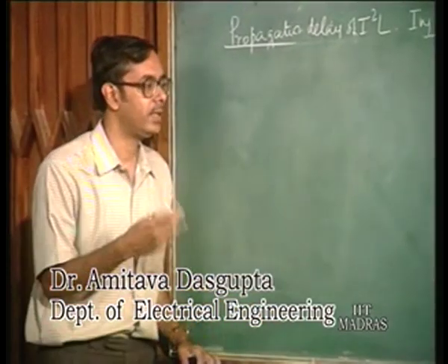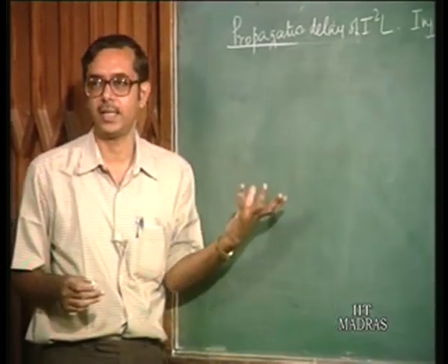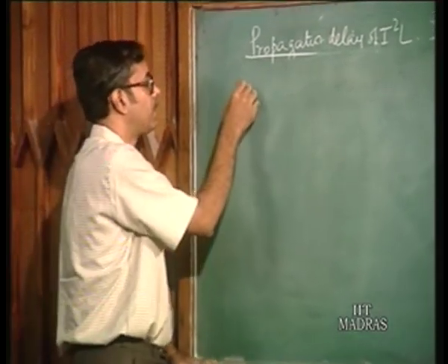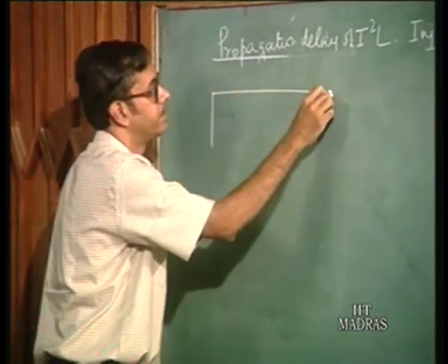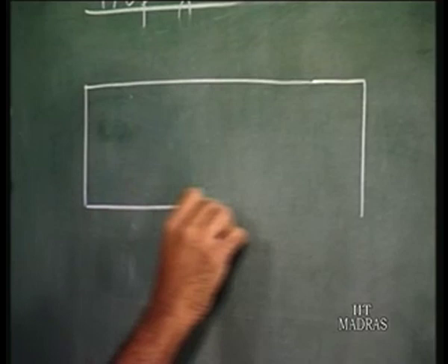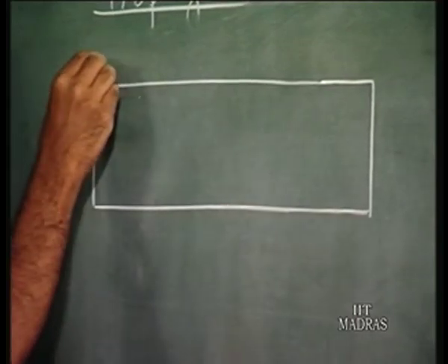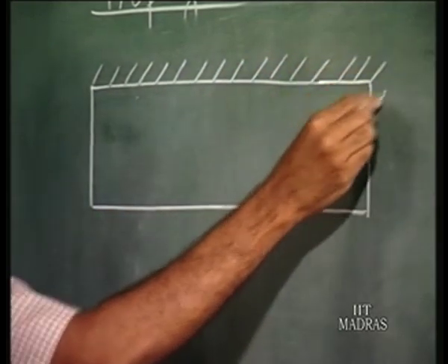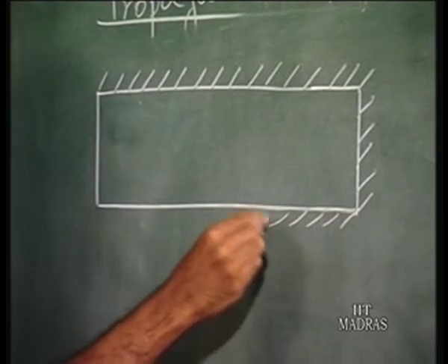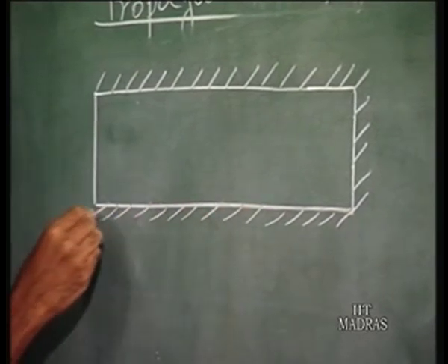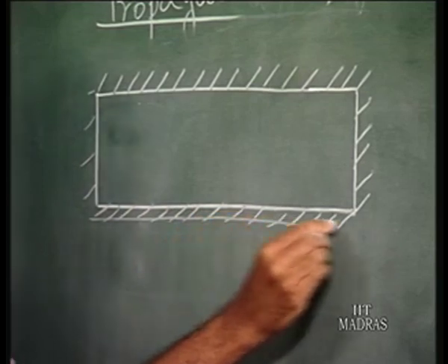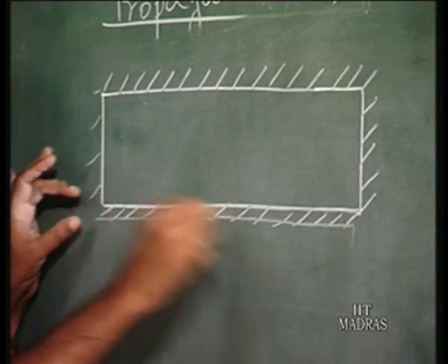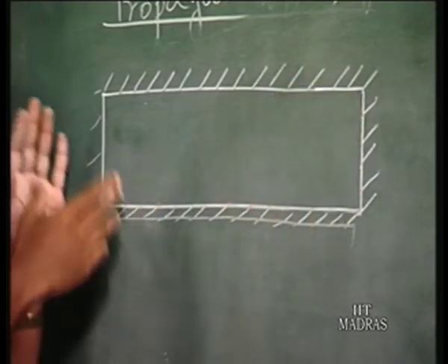So again in that self aligned process one uses oxide isolation. The first step is you define the active area. Active area means where you want to make the I squared L cell, and in the surrounding regions you have oxide, silicon dioxide, to isolate. In fact you may have other cells side by side, other active regions which are separated by these oxide, silicon dioxide.